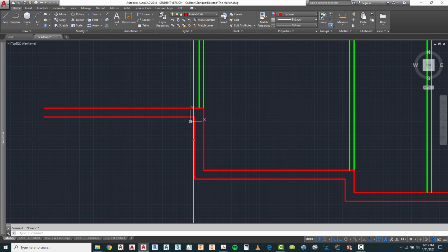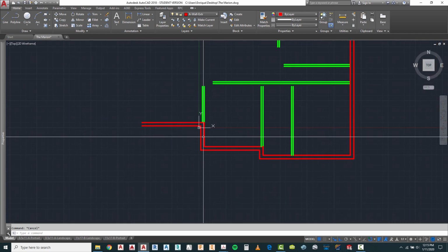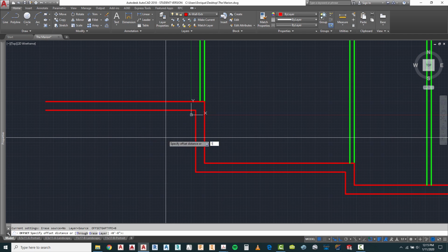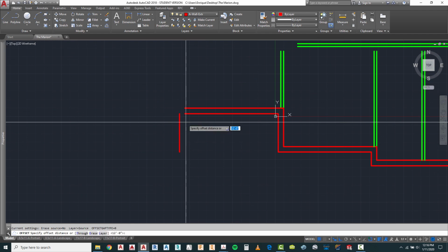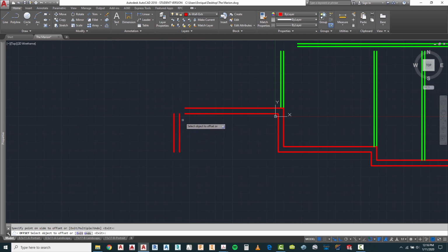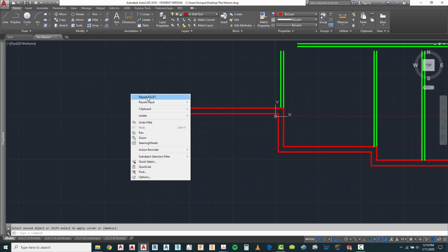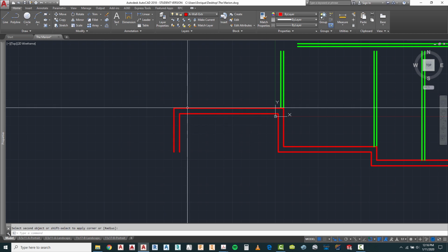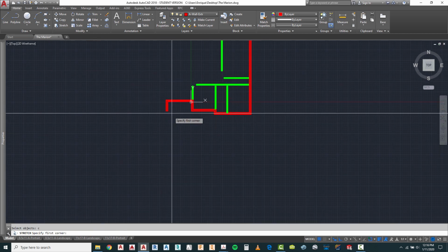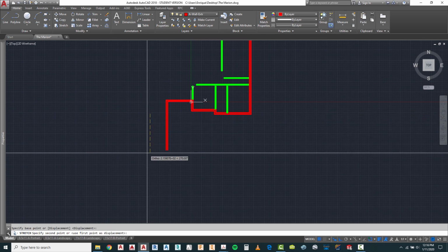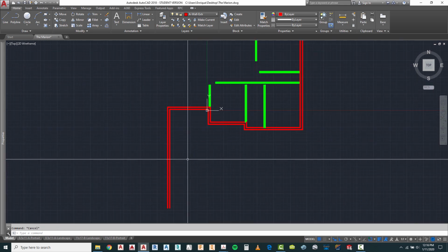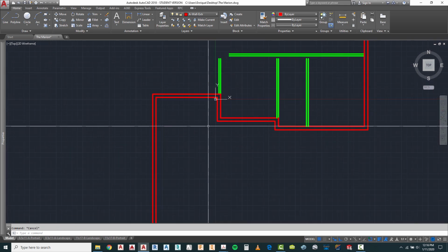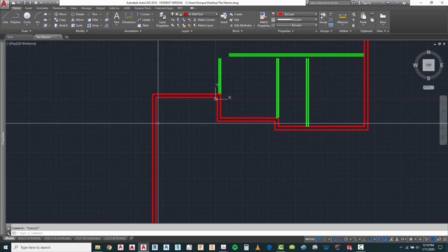The next thing that we're going to do is, we know that they want this porch to be 12 feet wide. I'm going to offset using 12 feet and then offset again to create the exterior wall here, and the fillet command to fillet our walls in here. Now I'm going to use the stretch crossing command and start to bring this down a certain distance. I don't know exactly how far that distance is, but I'm going to bring it down that far in here. Now our porch is lined up right in here.